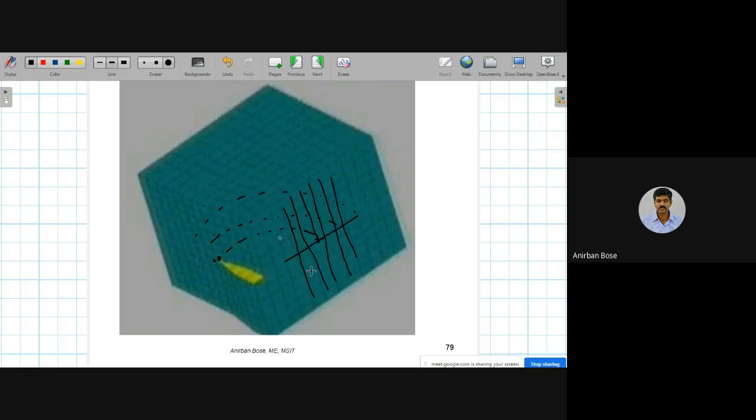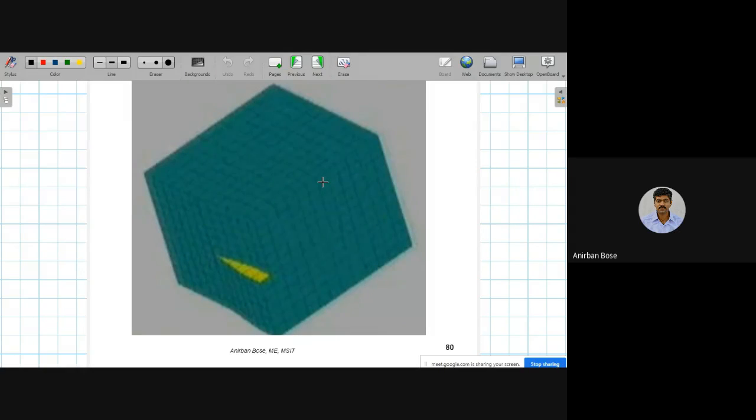So what you will observe in the crystal is that this edge dislocation is gradually shifting in this direction, and at this point you will find that the screw dislocation is shifting, and all the inner mixed points are gradually moving in that direction. So this is the way by which the whole dislocation motion will take place. It's very difficult to see that part, I know.